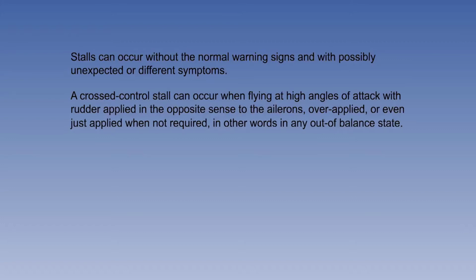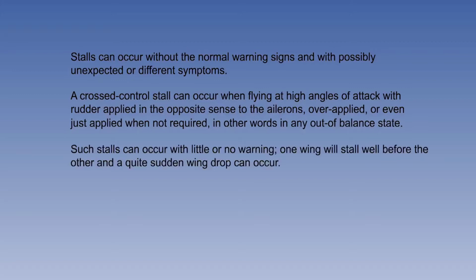This state will be confirmed by the displacement of the ball in the slip indicator. Crossed control stalls can occur with little or no warning. One wing will stall well before the other, and a quite sudden wing drop can occur.